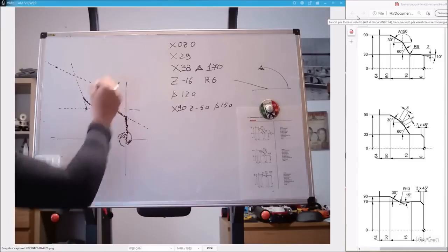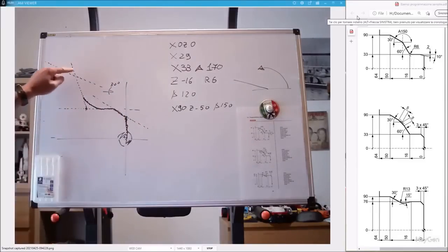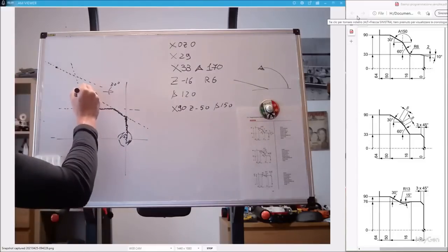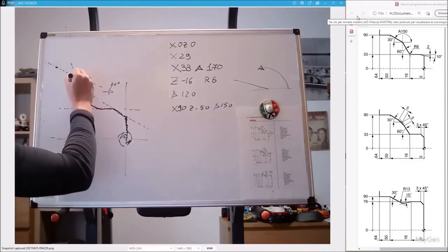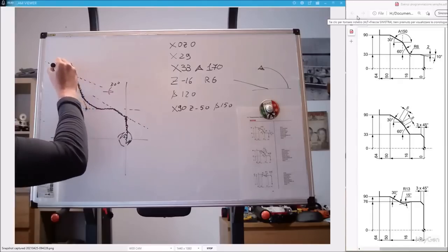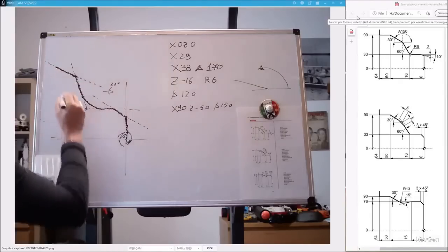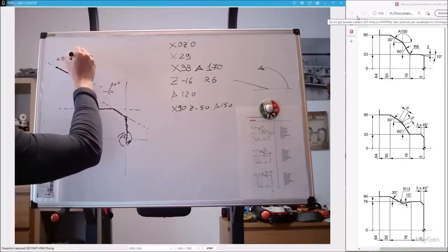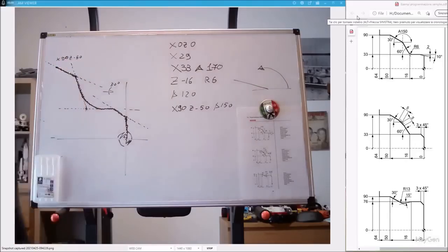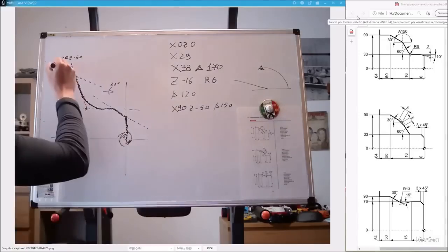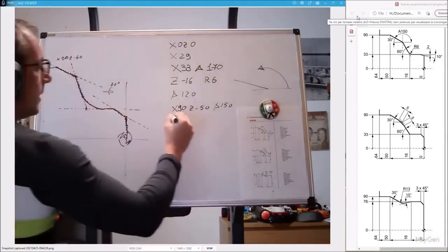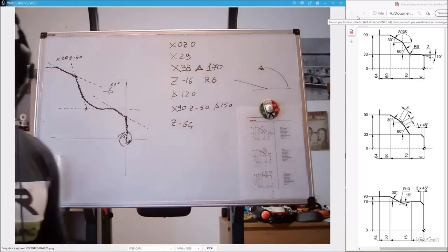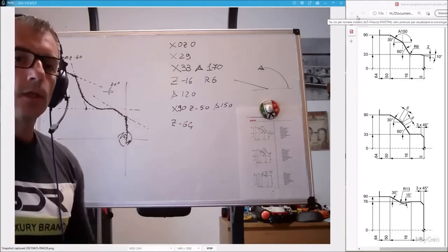You see that now the machine in its head has all the perfect building elements that I can get here. So this is the point x90, z minus 50. Well, I can give it the final z, which is z minus 64. As you can see, it's very easy.